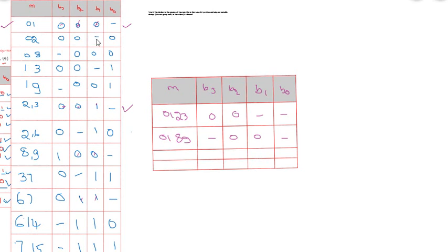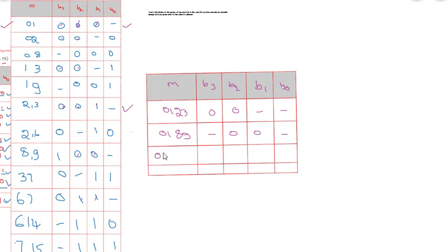Now go with the second dash. The second dash is present in 02, and similarly in 13 also there is a second dash. The last bit B0 is the only one that differs here, and B3, B2 are similar because B3, B2 are both 00. So we can make the grouping of 02, 13.